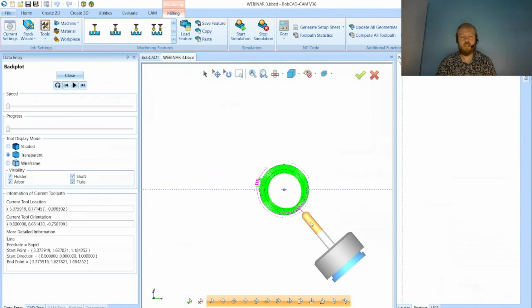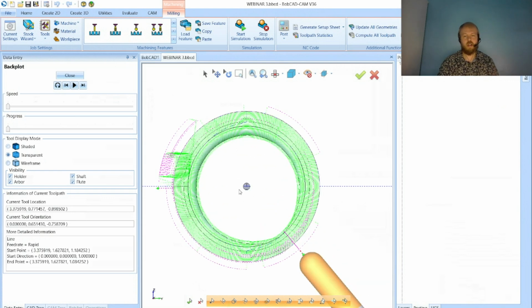It'll move up and down in Z, and it'll move back and forth in X while the part's being rotated simultaneously, but it doesn't move back and forth in Y off of the center line of rotation while the part's being rotated. So it's sort of like a 3+1 in the 4-Axis Standard, where the 4-Axis Pro offers 4-axis simultaneous machining.